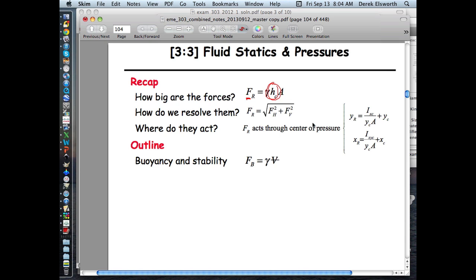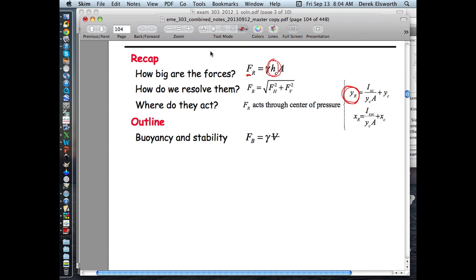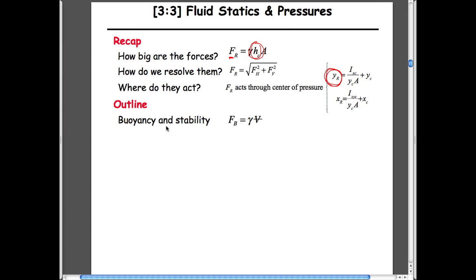If you want to calculate the point of action, then we can calculate it from the in-plane depth along the plate to where the resultant acts, and that is at some point slightly below the depth of the centroid, the y-coordinate of the centroid. And so one way to perhaps look at that, it doesn't seem so useful to do it the other way.